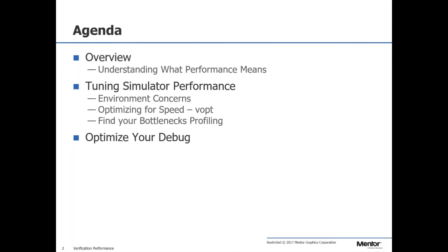Then we'll talk a little bit about how to tune the performance of Questa for various purposes, for regression runs, for debug runs, etc., and how you go about doing that. And then the last section we'll talk about is optimizing your debug, so getting performance out of your debug.